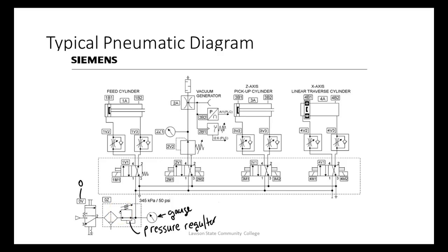So that means we got the cap. What you have to do on most of these is you have to pull them up, keep them from accidentally turning. Then you can adjust them. When you get through, you're supposed to lock them back down, right? That way somebody can't accidentally do this. And what do we say this was? Filter. We call this a service unit because we could have all these things individually, but these things are all built in one unit.